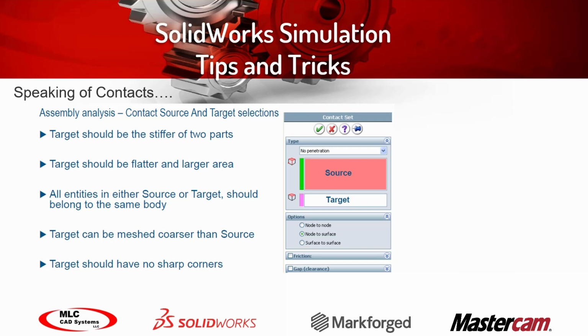On contacts, when you're setting them up, I have the larger, more stable object in the bottom, and in the first definition, or that property manager in that top box, I'll put the one that is less stiff or more subject to move. The target can generally be meshed a little bit coarser, but again, you still want to keep in mind the idea of convergence, mesh validation, aspect ratio, two elements through the thickness, all the other things that I've already mentioned.